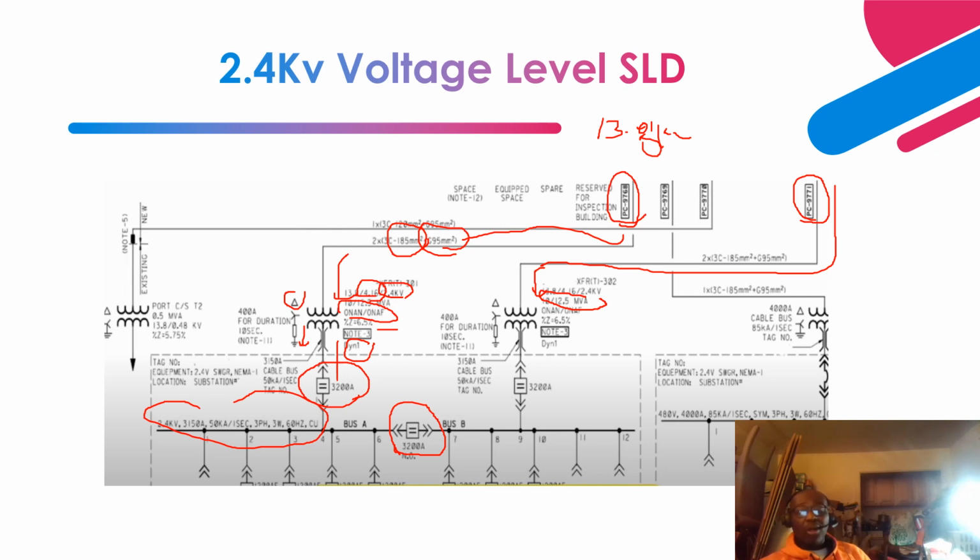That is the natural convection rating, the natural flow of air over the surface of the radiator without any fans. And the 12.5 MVA is the ONAF rating. That is forced air. Basically, the transformer has staged cooling fans blowing air over the surface of the radiator to remove the heat, to be able to achieve the average temperature rise within the design specification.